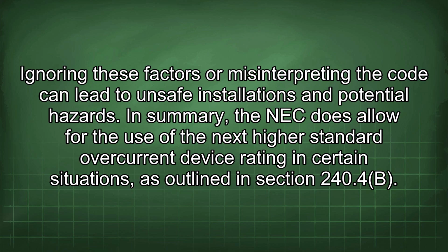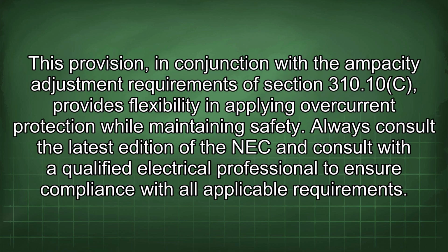In summary, the NEC does allow for the use of the next highest standard overcurrent device rating in certain situations, as outlined in section 240.4(B). This provision, in conjunction with the ampacity adjustment requirements of section 310.10(C), provides flexibility in applying overcurrent protection while maintaining safety. Always consult the latest edition of the NEC and consult with a qualified electrical professional to ensure compliance with all applicable requirements.